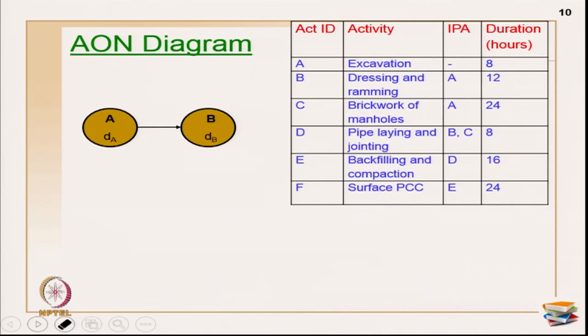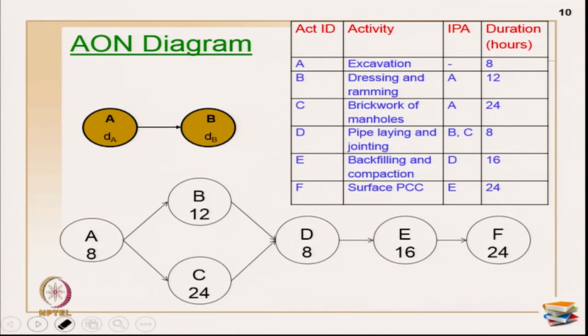Now, let us move on to the other form of CPM representation, which is an AON diagram. So, the same example I am going to take. The same example I have taken, duration, everything I have taken from the previous example which I was listing out right now. Okay. So, now how do I represent this example? As I have told earlier, activities are generally written inside the circle, but above, and the durations of those activities are written below, but inside the same circle.